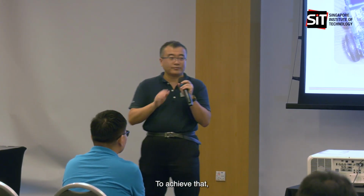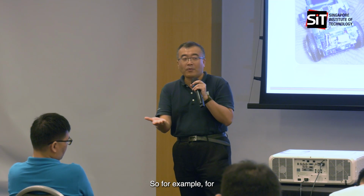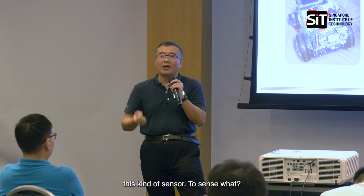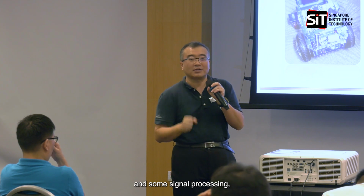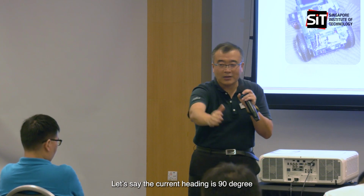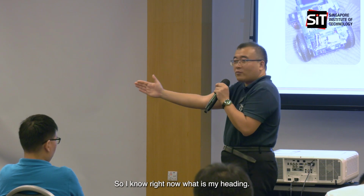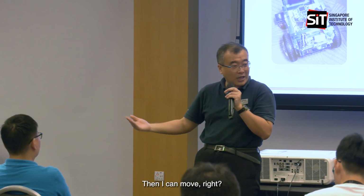To achieve that, inside we need some sensors and analysis. One example is the so-called IMU sensor, which includes the accelerometer and the gyroscope, to sense linear acceleration and angular speed. By analyzing this with some signal processing, we can know what my current heading is. Let's say the current heading is 90 degrees and I need to turn to 0 degrees. So I keep calculating, so I know what my heading is right now. If I know my heading is 0 degrees, I stop. I know the turning is done, and then I keep moving.